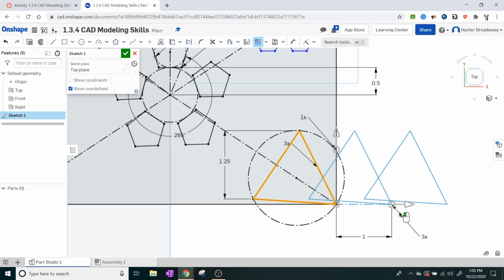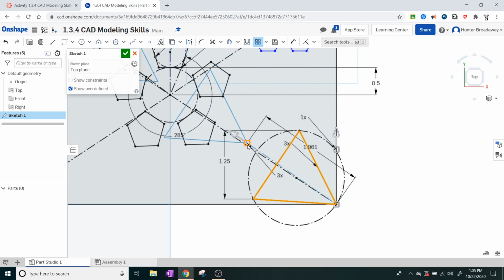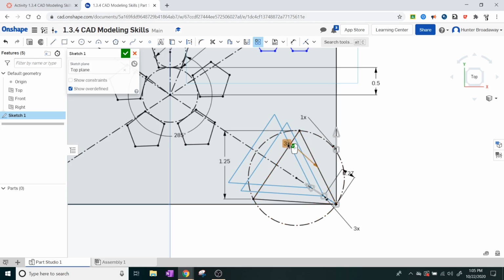And I want them to not be based on, see this arrow right here? I want to try to drag them around so that they're going this direction in the line of this construction line. And I'm going to squeeze them into place to make them a little bit closer together. And notice they're the same space apart from each other. It looks like I can squeeze about 1 or 2 more in there. So I'm going to change this 3x to 5x.